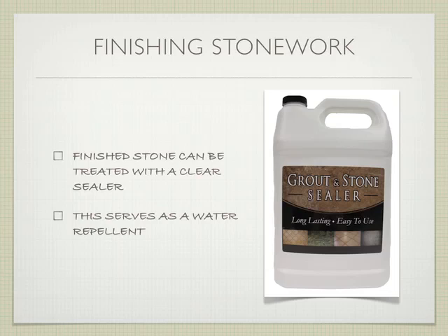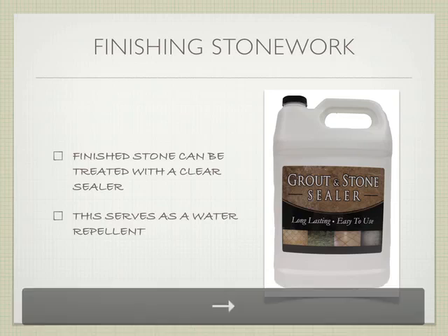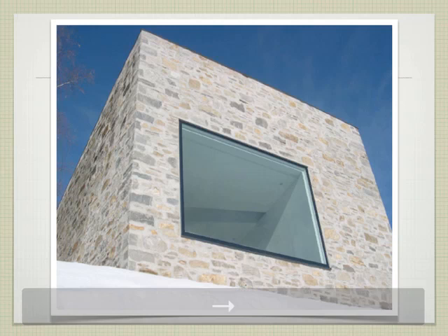And for whatever reason they decided to seal it, probably has to do with underwater conditions and not letting the water go through those pavers into the subsoil or whatever, which is a whole side note because a lot of times engineers actually want you to let the water go in so you're not collecting the water and then putting it somewhere else. So there's big challenges related to that particular thing. The other thing that can happen, though, if you seal the stone, is it can make it slipperier when it's wet. So you have to be aware of which sealer you're using and what it does. Not all sealers are shiny, so certainly you could seal a particular set of stone without doing that.